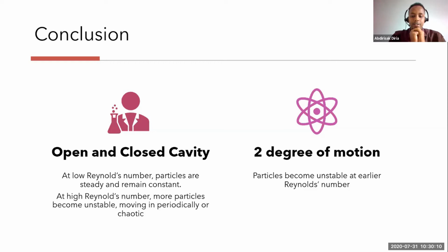In addition to that, what I observe is the fluid inside the cavity in my case is incompressible, which makes the flow's Reynolds number the dominant parameter. So if we change the density, it might change, but it's not noticeable. But if we change the Reynolds number, increase or decrease, it changes a lot. And that explains the definition of Reynolds number, because it's the ratio of inertial forces to viscous forces. So that makes sense.